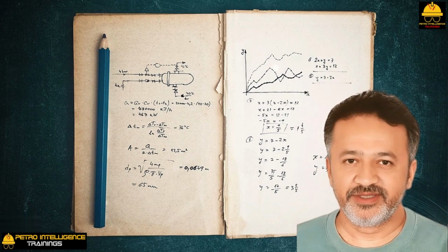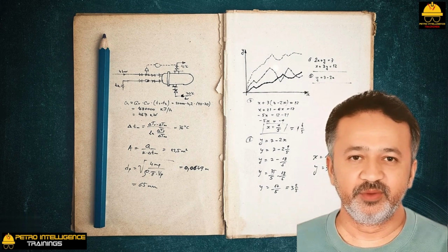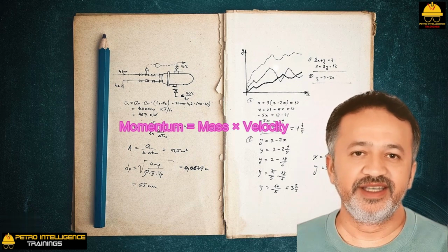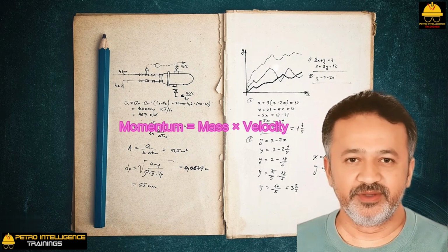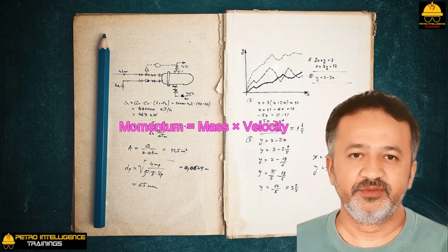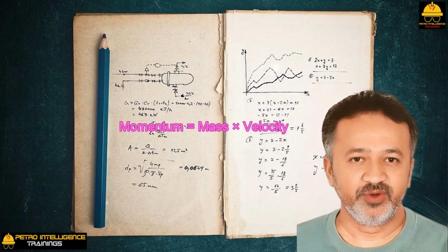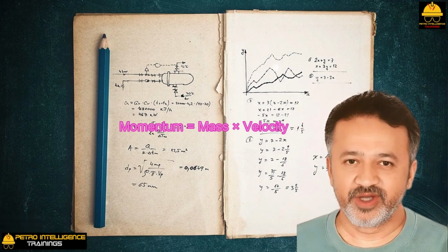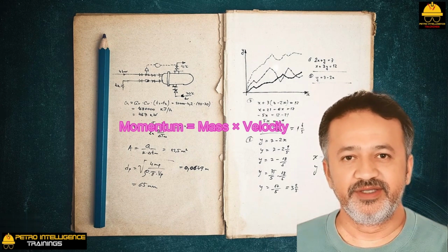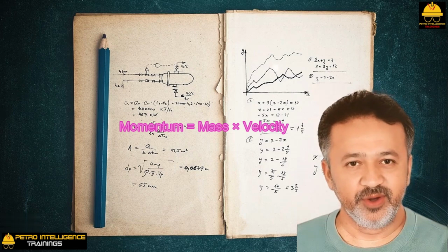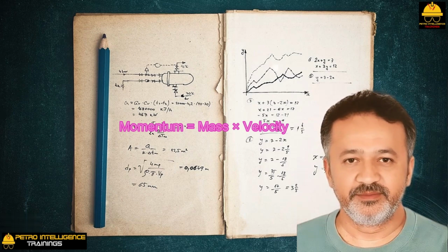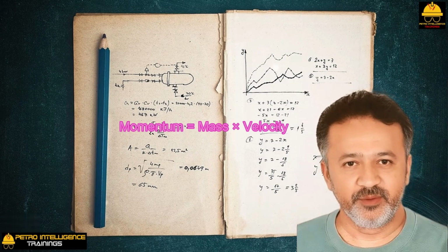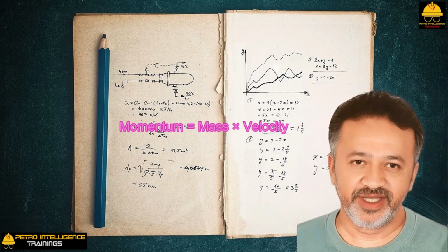Momentum in steam turbines. A useful way of summarizing the concepts I have just related is to think about momentum. That is, momentum equals mass times velocity. When we operate a steam turbine, we are trying to provide a certain amount of horsepower to drive our pump, or compressor, or generator. If I want to provide this power with less mass of steam, I need to increase the velocity of the steam. And this is done by extracting more sensible heat from the motive steam, and more importantly, more latent heat from the motive steam.